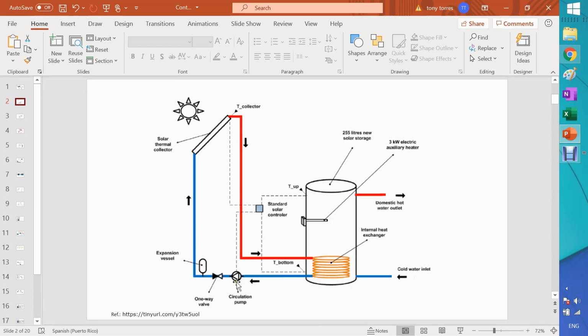Sometimes you don't want to run this pump at high speed when you can do it at a lower speed, and so forth. Again, this is a closed loop type because it's using a heat exchanger coil, and domestic water is right at the outside of the coil. Within the coil, there's sometimes glycol. All right.